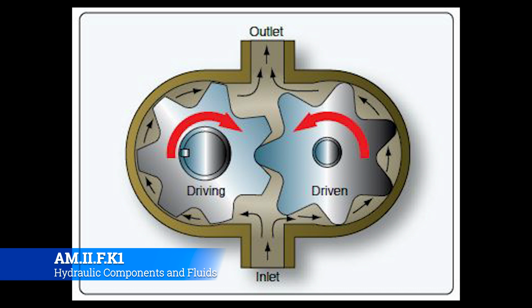Well, that tells me that the pump is starting to go out, and the likelihood is that those little sprockets are starting to wear down, so now there's more and more of a gap between them to hold hydraulic fluid. And if there's a bigger gap, there's probably less pressure, and then you can extrapolate that out. That's why we go into these different classifications of pumps, so you can think through the problem rather than just shotgunning parts, changing one thing or the other. But anyways, that is a gear type pump, and next we're going to go to the gerotor pump.